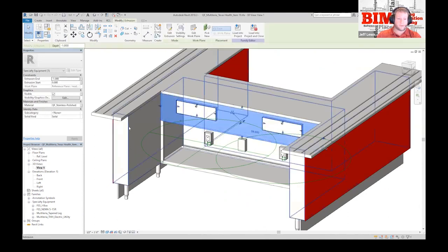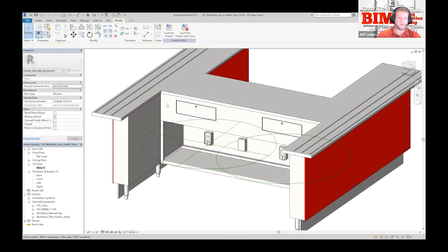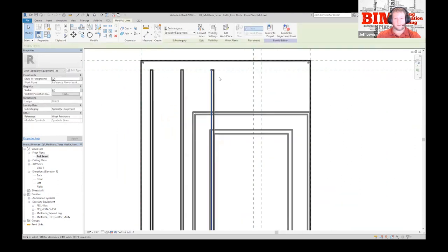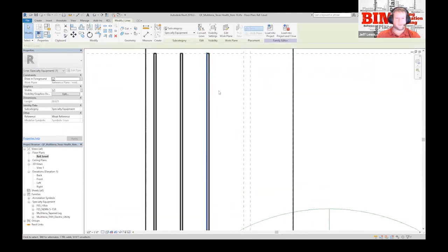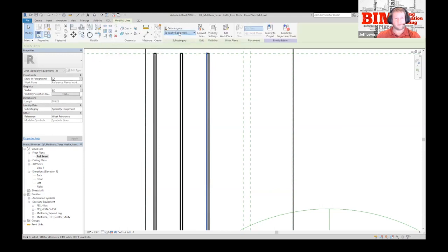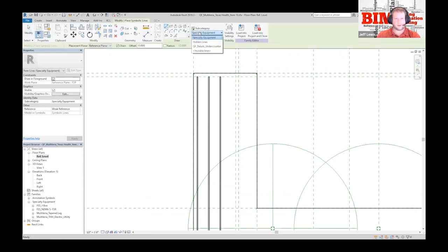As you can see, all 3D geometry is turned off in plan view. This helps when it is being laid out in the plan view of the project. It does not bog down the computer's computing power and lets you scroll things around. Anything that needs to be seen from the top, as you can see here, I've got in what's called a wireframe. Go to hidden, and this is all we need to put any symbolic lines under specialty equipment. Anything that is going to be beyond that symbolic line, we want to put under counter details if needed.